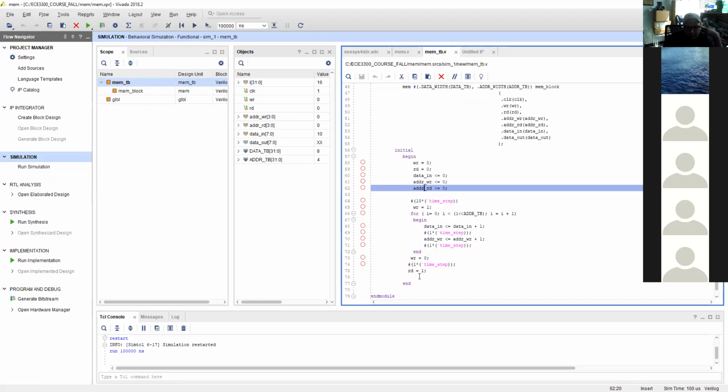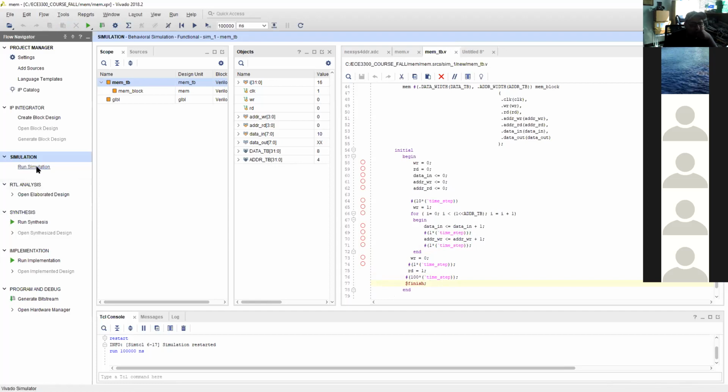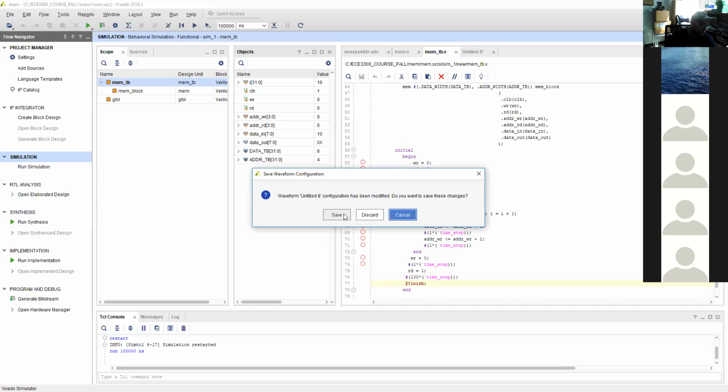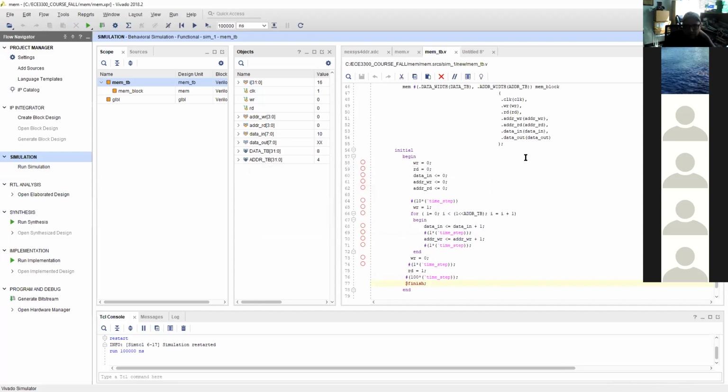So let's see. And then, for instance here, wait for some time, which is this time. Say, wait for instance 100 cycles, and from there you can just say finish. After 100 cycles, finish. I'm expecting that by the end, the value of data out will jump to whatever was written before, and we wrote 1, so it should be 1, I believe. So let's see.